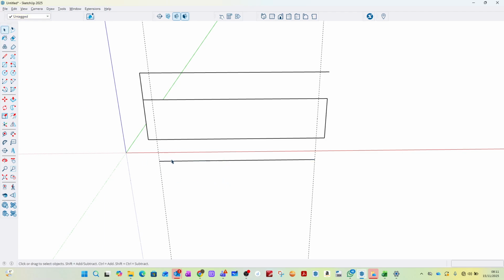I'm going to just delete a couple of these elements that were divided so I can see where my segments are. What did I do there? Right, what did I do? I used the tape measure tool, snapped onto the end point, and I pulled up, and I used the up arrow key. I'm just projecting up a temporary construction line. These lines will be very helpful in a few seconds.